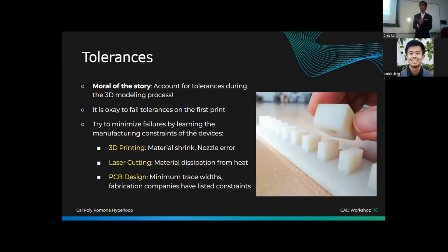Laser cutting, if you design for it, also has its own variances of dimensions. So you can't do exact measurements; you have to allow some variability. If you want to manufacture a really precise object with a really small tolerance, it costs a lot more to do. With 3D printing, since the allowed variability is large, it's going to be a lot cheaper to manufacture.